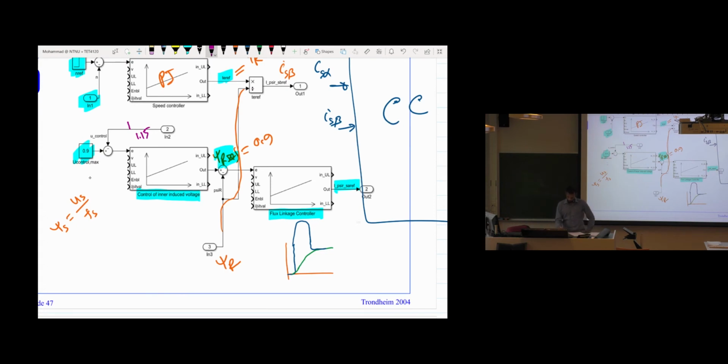You can see it's 0.9 minus 1.15. It gives us some negative value. So we are getting a negative value, and it comes through this PI controller. So it's reducing the flux reference. Since it's giving the negative value, it's reducing this flux reference. Instead of 0.9, maybe it gives a little bit lower, so that we can apply the field weakening. So that's how we can select.